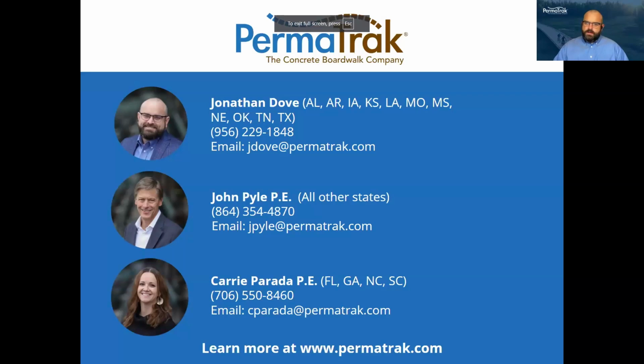Perfect. Thanks, Jason. Then we had a question on if we're under 30 inches, is a curb required? John, you want to touch on that? It's my understanding that a curb is not required if you're less than 30 inches. Again, I go back to thinking about those beach access, dune crossovers. A lot of those, there's nothing on the side there. I think the 30-inch and less and having a curb on there is user preference, is owner preference. It's always good practice, but it's certainly not required.